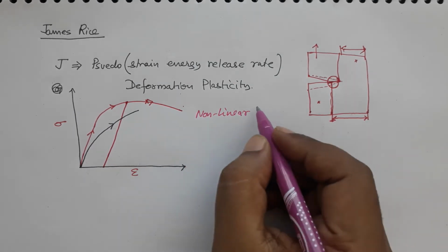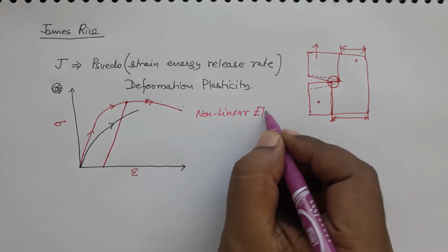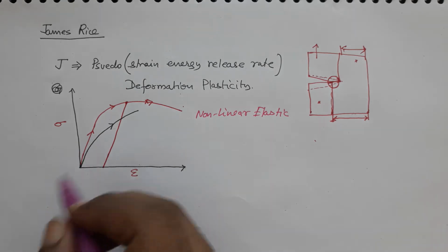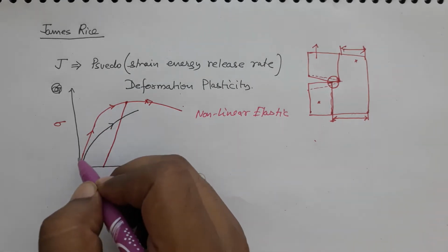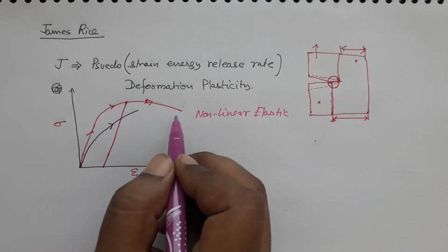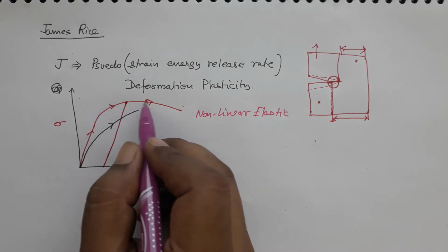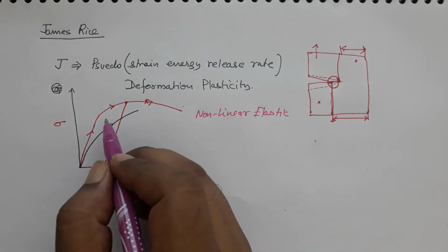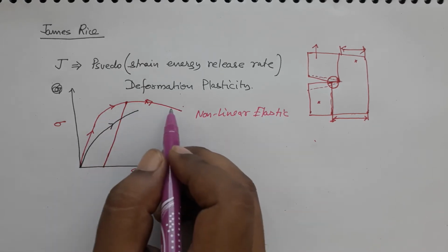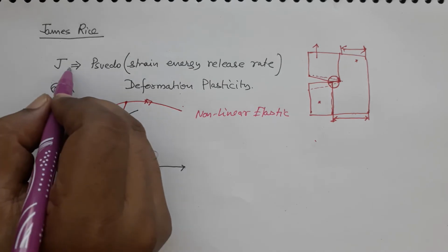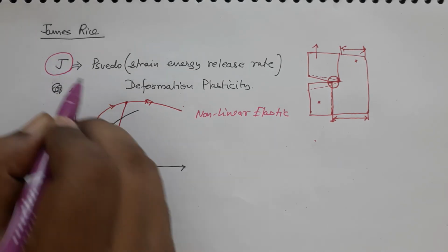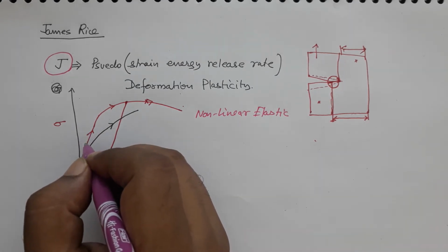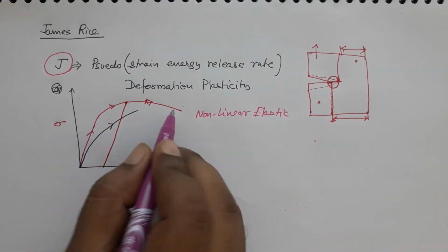Why was it done? Because metallic materials and other materials, almost all materials except if they are very brittle, usually deform plastically, right. So, if you have a plastic deformation, that is obviously not linear, but you cannot entertain an irreversible phenomenon if you want to put something like J integral in the application. So, Rice assumed that the material is deforming elastically.